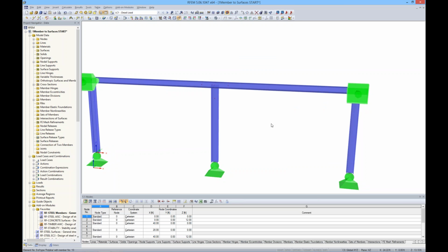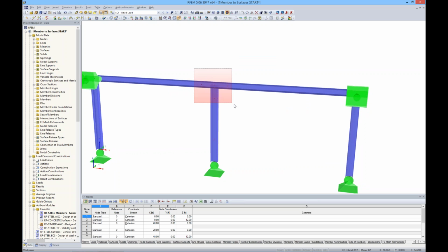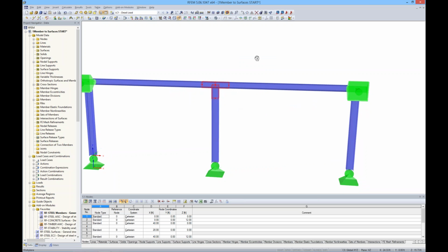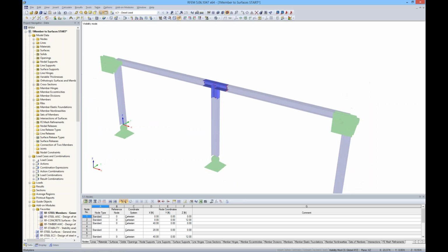So I'm going to go ahead and render it again. And I'm going to select these. And the selection is just similar to AutoCAD. If I drag from left to right, it will only grab what's in that box. If I go from right to left, it will grab everything that that box touches. So for this case, I'm just going to select here. And I'm going to choose a visibility by selected objects. So now I can no longer select anything other than these 3 elements that I specified before.